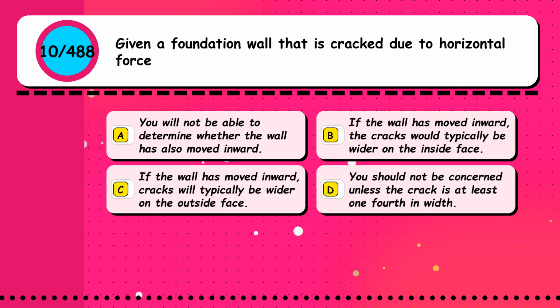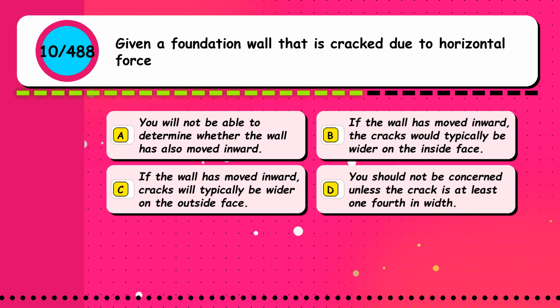Question 10. Given a foundation wall that is cracked due to horizontal force: Option A. You will not be able to determine whether the wall has also moved inward. Option B. If the wall has moved inward, the cracks would typically be wider on the inside face. Option C. If the wall has moved inward, cracks will typically be wider on the outside face. Option D. You should not be concerned unless the crack is at least 1/4 inch in width.